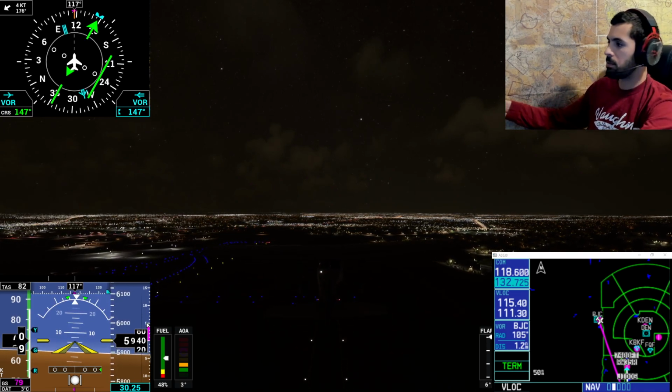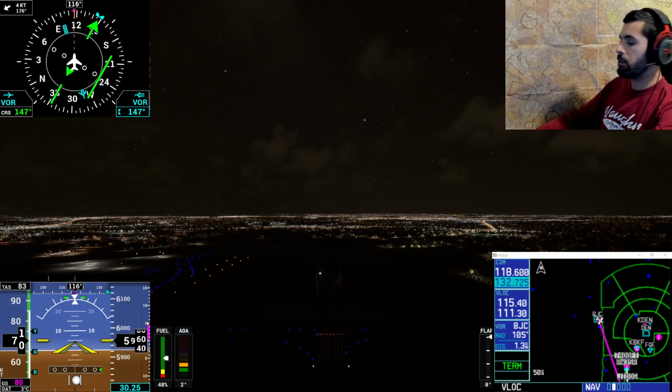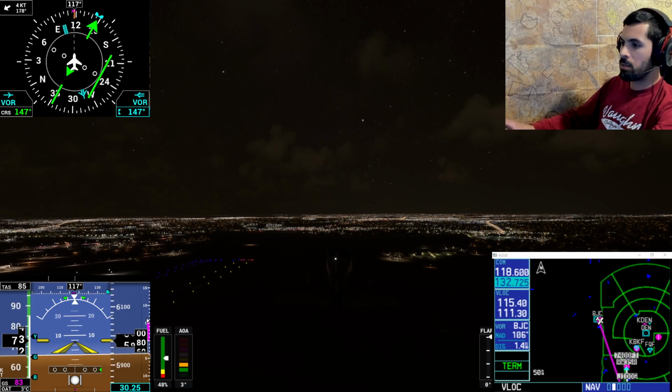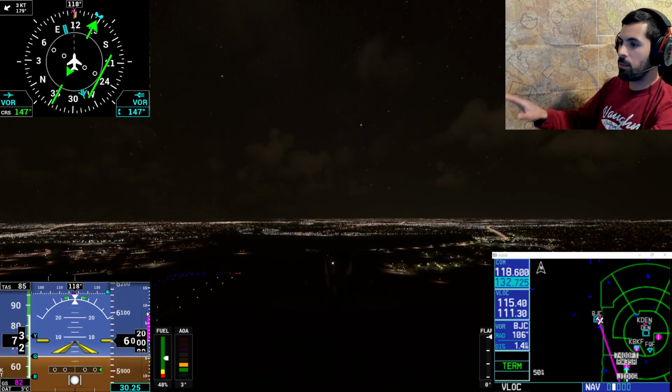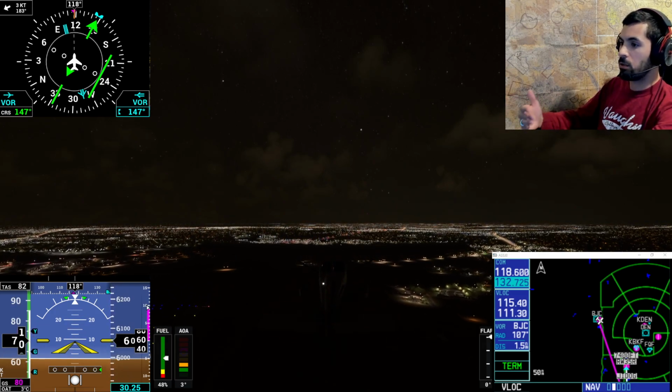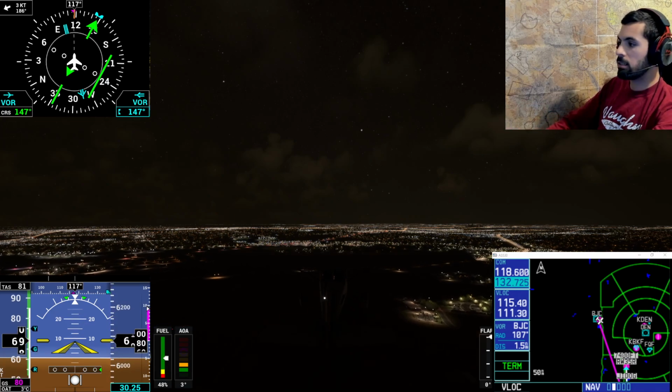We're going to pick up those flaps. That's going to reduce my lift, so you'll see my airspeed pick up because my nose drops a bit. We're going to compensate for that by picking that nose right back up almost to 10 degrees, and you'll see that airspeed starts to slow down. Really looking for 65 knots.